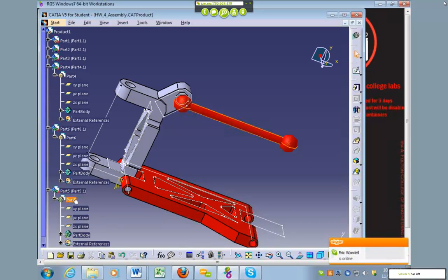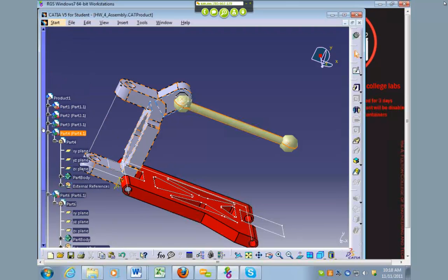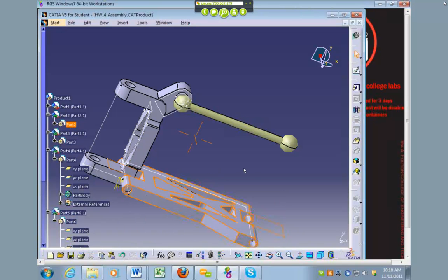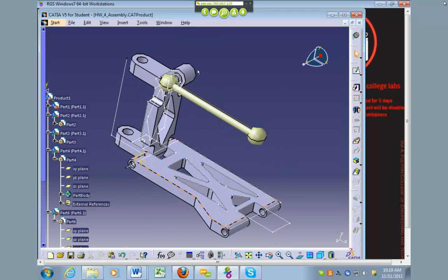So if you go back into Lab 4, you'll see that we've got all of the different parts there. There we go. And so what you'll do is you'll do a mass properties analysis on this assembly, and then you can change the parametrics that are in there to make it wider, taller, shorter, shallower. And so then using that information, you guys can see how much those mass properties will change.